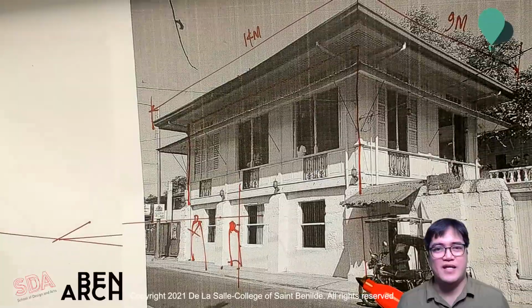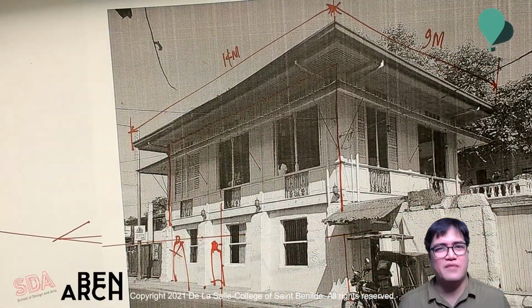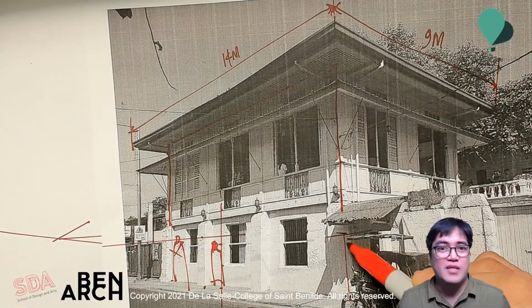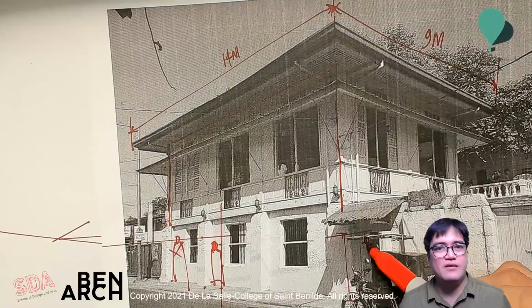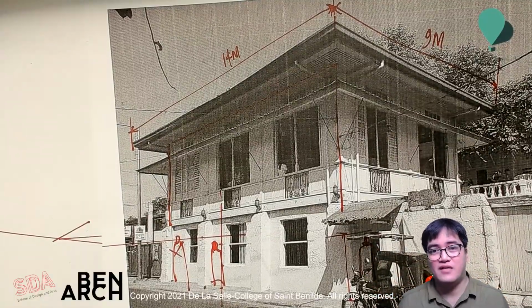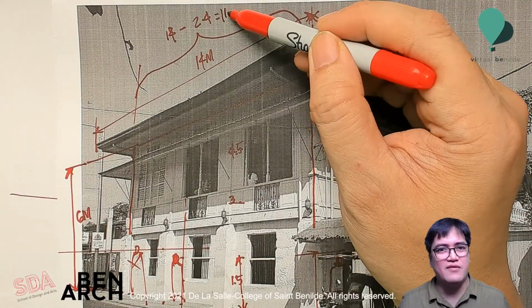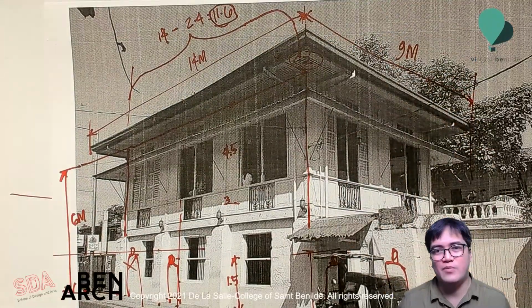So step number 2, it would always be easier if you can get a picture reference facing the facade or elevation you are drawing. I determined that the eye level is usually about 1.5 to 1.6 meters when somebody is taking a picture normally. This is important because I can determine or intelligently guess the height level based on this information.